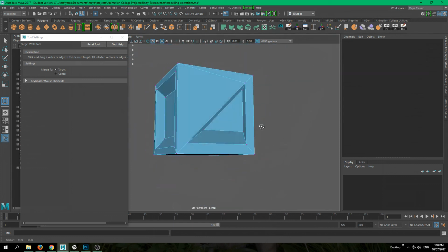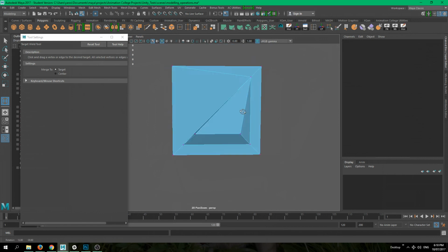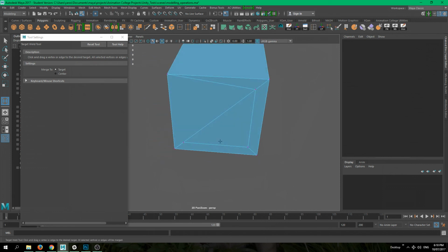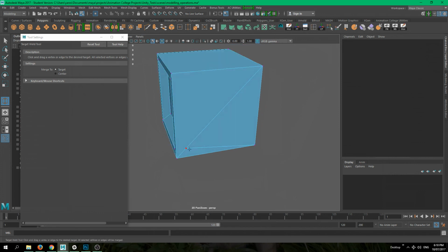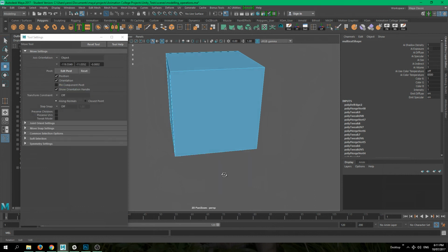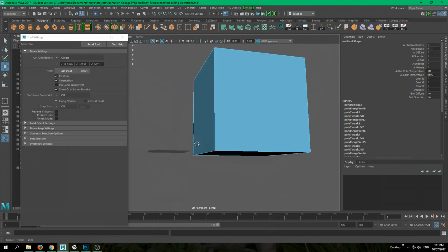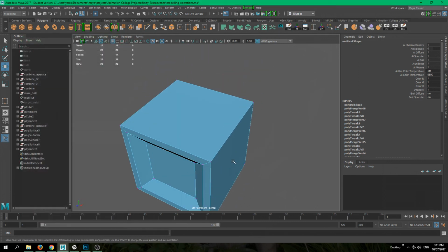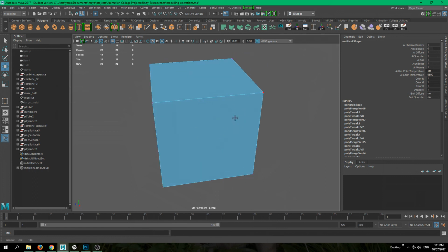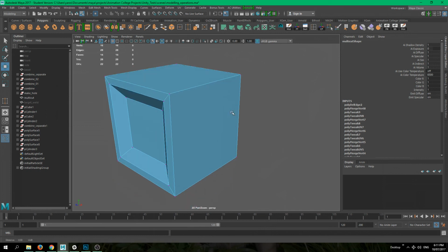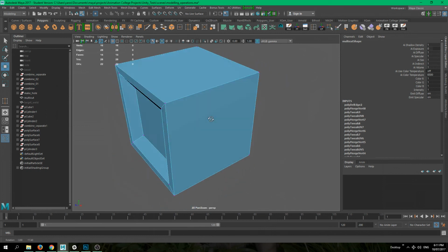So we can start introducing some quite cool shapes if we wanted to, or we could just go ahead and get rid of this extrusion altogether. And we can keep combining elements until there is nothing more left, except for this one edge, which we can just click on and go Shift right click and delete edge. And there are no vertices or anything like that. So this weld tool is really cool, and especially when you start finding n-gons, when you start finding those floating verts around, this is where you can just use your target weld tool, if nothing else helps to get rid of those vertices. So really useful. Go ahead and try it out.